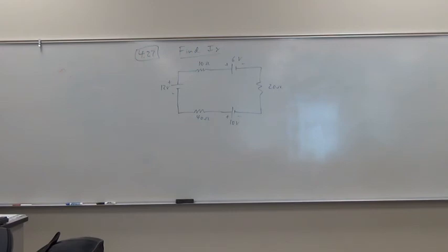Right? No, that's 10 volts. You don't have to multiply times ix. Exactly. But this is a minus, you hit. If you look here, see, your current's going this way, right? So if you use the passive sign convention, you would make this plus and this minus. So you should hit the plus side first. So you want this to be plus. That plus, and then this all gets set equal to 0.